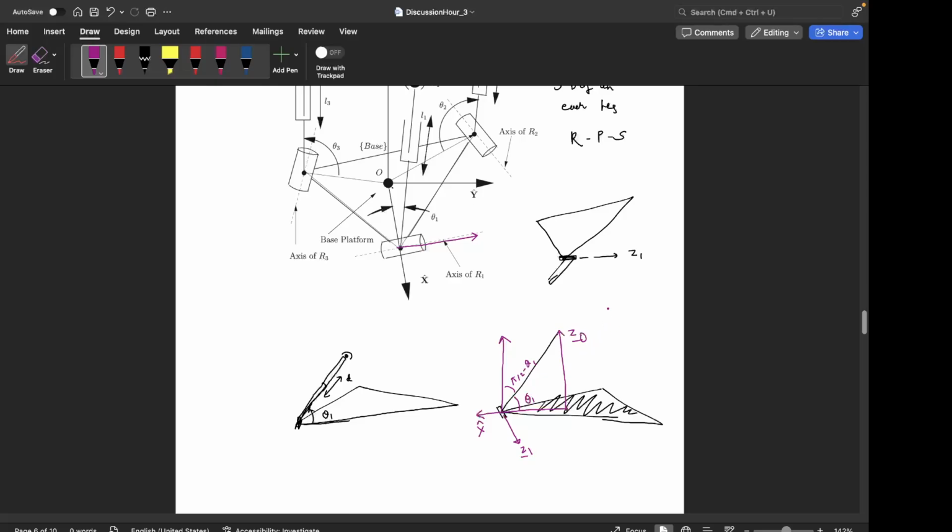And the joint angle is basically about Z, between xi minus 1 and xi. Isn't it about x between zi minus 1 and zi? I'm doing about the theta. Oh, okay. Sorry. That's fine. I'm just trying to reconstruct the frames, how they would have taken them.